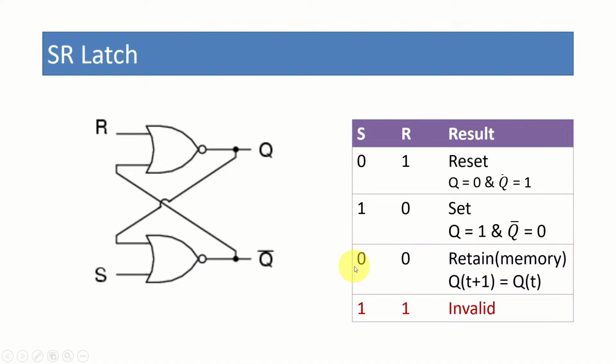And there's another important thing when it comes to the SR latch: we must never give the 1, 1 input combination to the SR latch because it results in an invalid situation. So if we move on to the 1, 1 situation, we have to clear the latch again. So let's try to understand how these things are happening at a conceptual level using our understanding of logic gates.